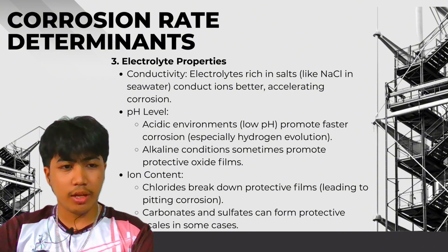And number 3, electrolyte properties. Conductivity: electrolytes rich in salt, like sodium chloride in seawater, conduct ions better, accelerating corrosion. pH level: acidic environments, low pH, promote faster corrosion, especially hydrogen evolution.